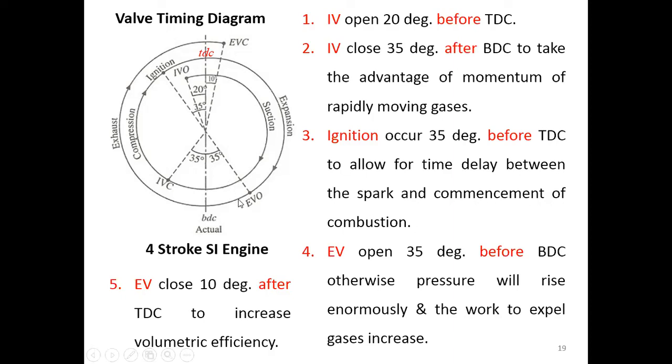Okay, so the exhaust valve opens at 35 degrees before the top dead center, and when the exhaust valve opens, that means the exhaust process happens and it finishes here. The exhaust valve closes at 10 degrees after the top dead center.